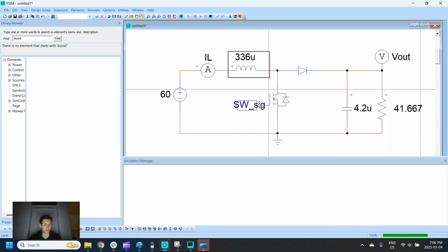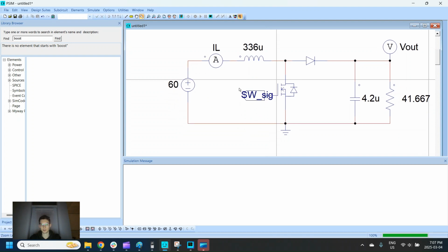But yeah, inductor, we went over, you choose one, you wind one yourself. Diode, again, you just choose one. We'll need the MOSFETs. We'll pick one that's for the select ratings, and we'll make sure that we have a buck converter to supply the power, or some sort of power supply to the gate driver, which you'll also need to select, and that'll be between the microcontroller and the gate driver.